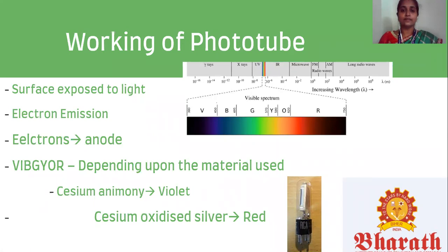Vacuum devices have a near constant anode current for a given level of illumination relative to anode voltage. The gas-filled devices are more sensitive, but the frequency response to modulated illumination falls off at lower frequencies compared to vacuum devices. The frequency response of vacuum devices is generally limited to the transit time of the electron from cathode to anode.